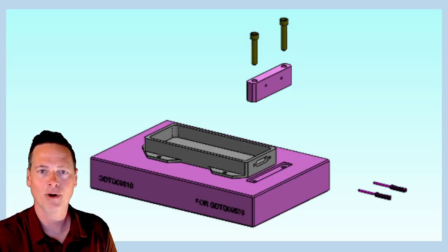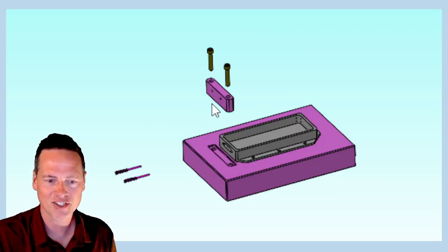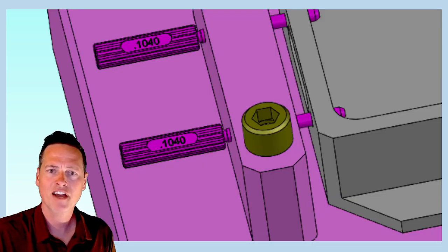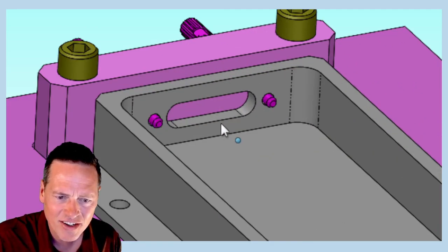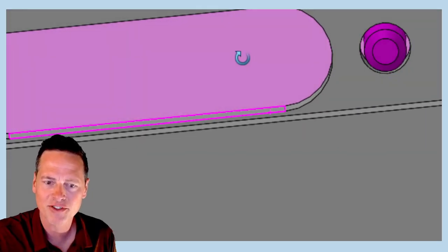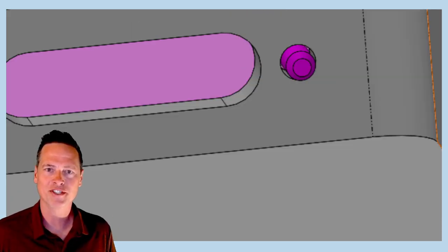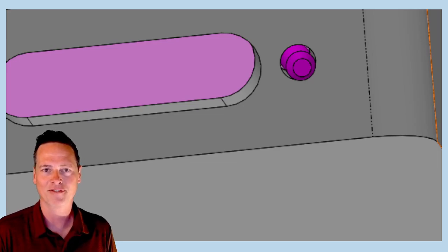And now if we go back to our inspection fixture, since we're having fun, what if we add a special block in here that's going to help us locate those holes in that datum reference frame A primary, B secondary? See how these pins are the 104 thousandths virtual condition? And that in here, well, there's quite a bit of clearance around those .125 nominal size holes. And that just shows we have a looser position tolerance in this callout. That's a good thing because these holes are probably drilled in another machining setup separate from all the other features that are made in this datum reference frame.